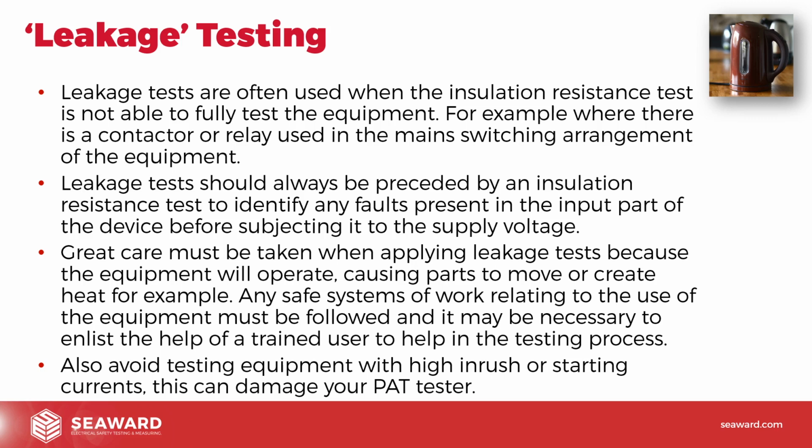So it's always advisable to start off with an insulation resistance test, because that's a safe voltage generated by the tester. It's not a mains voltage. It's a voltage generated by the tester, so the current is limited and things like that. What we can do then is actually get a picture of that without putting ourselves at serious risk. Whereas if we're taking a piece of unknown equipment and the first test we're going to do is plug it into the main supply, if we can avoid doing that, we really should. So we always advocate doing an insulation resistance test before we do any of these mains powered tests.